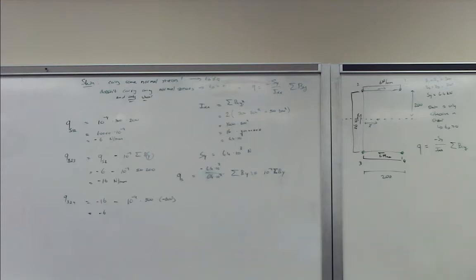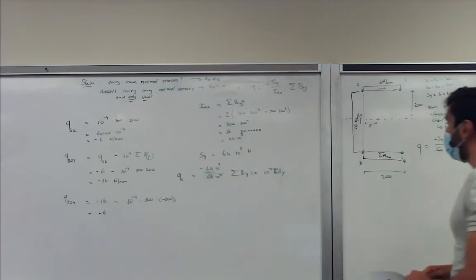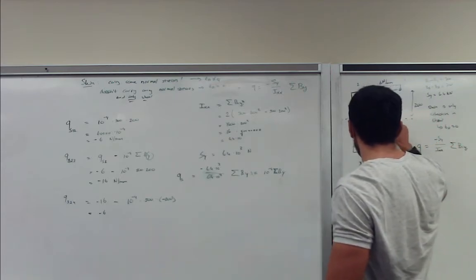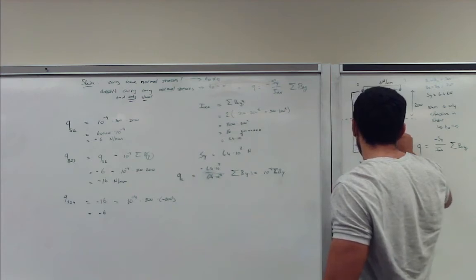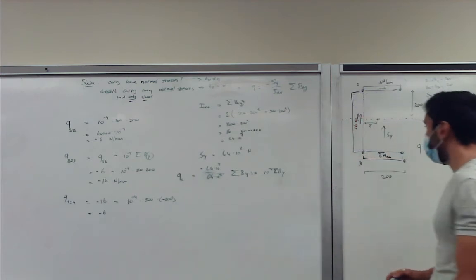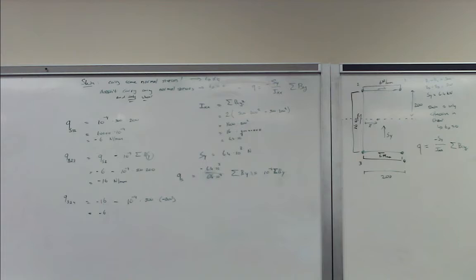Could you show where the Sy is applied? Sy doesn't matter where it's applied. It's given as applied through the shear center, so it doesn't create any twisting moment, but it will be in the opposite direction of the positive, otherwise it would be a negative number. So does it matter if the Sy is located to the right or to the left side of the shape?